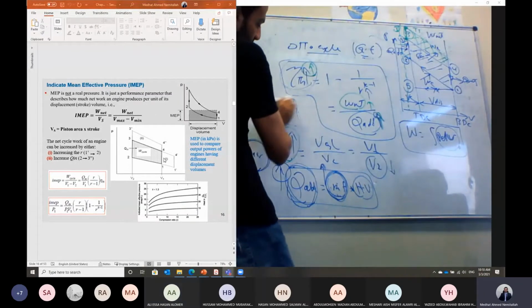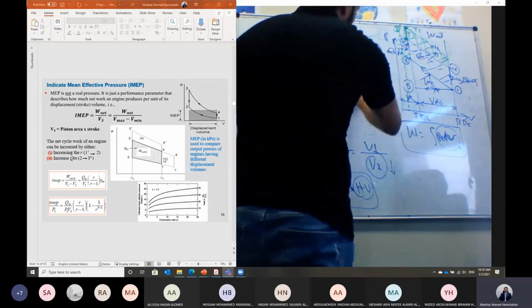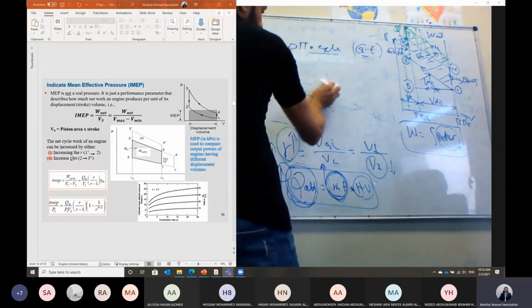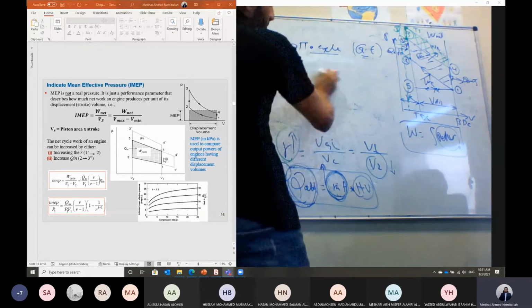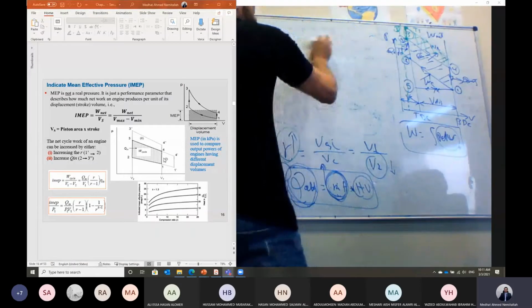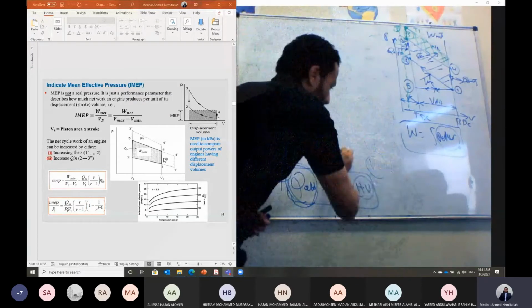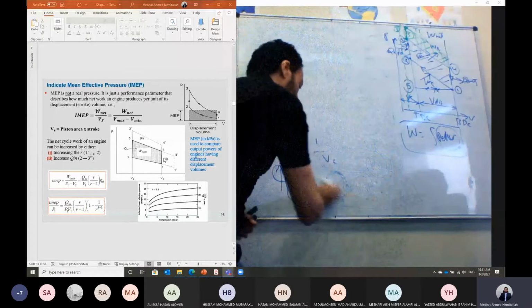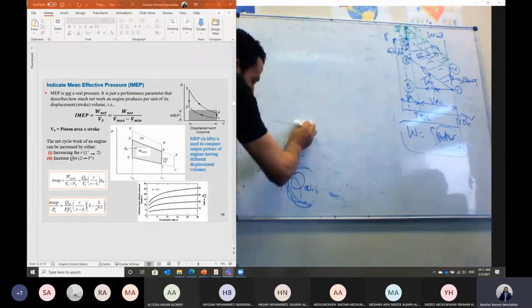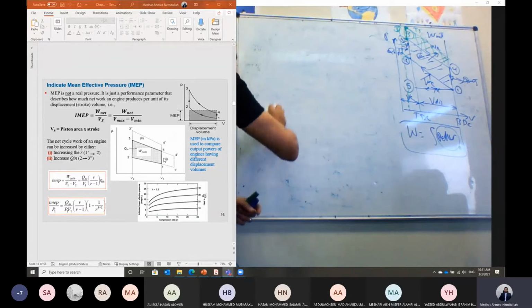So this is the efficiency. As I told you, Shabab, this efficiency for the Otto cycle is a standard cycle in which we assume we don't have any losses within the system. All processes are reversible. A reversible process, Shabab, means a process can be reversed without any effect on the system. We don't pay any kind of energy to reverse the process. That means this process has no losses, and also we assume we don't have any losses from the engine to the cooling circuit or anything. So that's why this efficiency gives us an indication about the limiting efficiency of a gasoline engine that cannot be reached in reality.